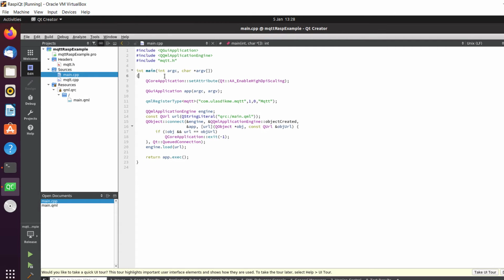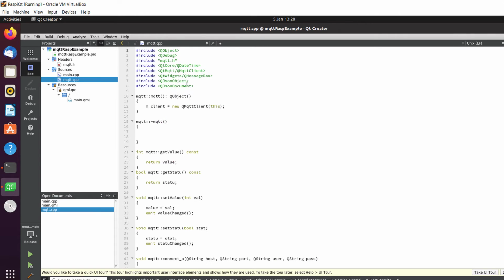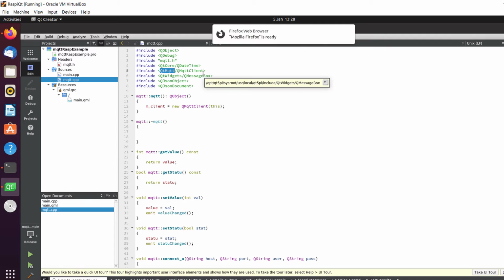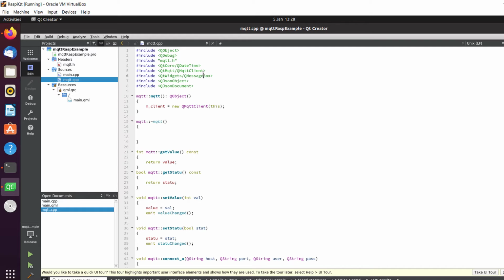I found a simple one, I think, yeah, the QtMqtt library. I just compiled it here with my qmake for the Raspberry Pi. I just did it before, so it's simple work. It's cool. Then I will show you right now how you can port it to your application. Also, if you follow my old video for this, then you can already do this in the same way.